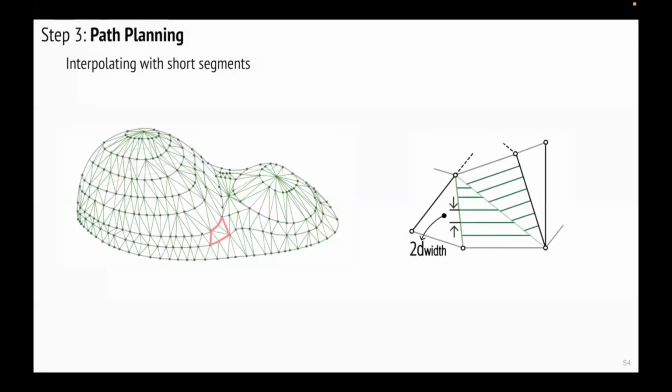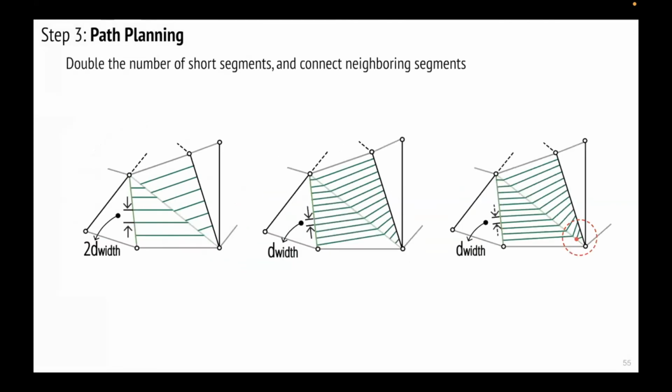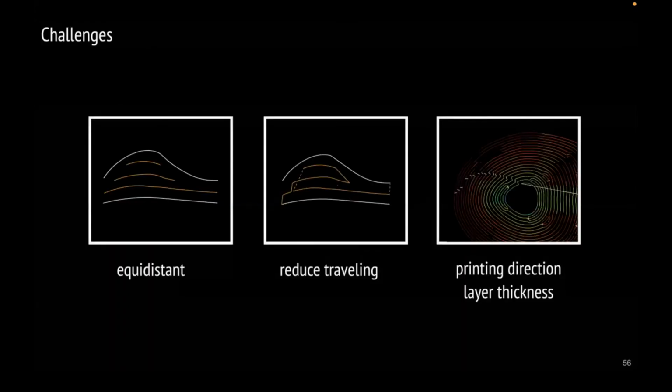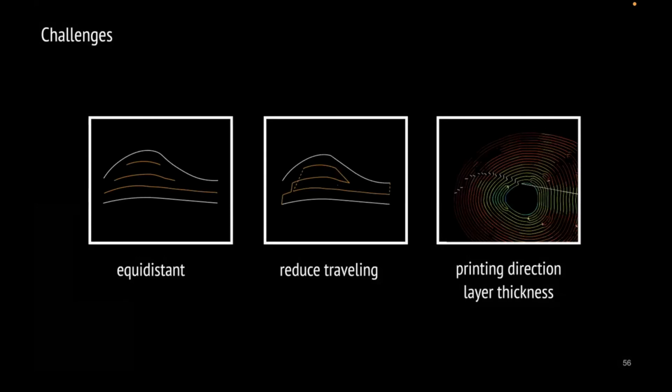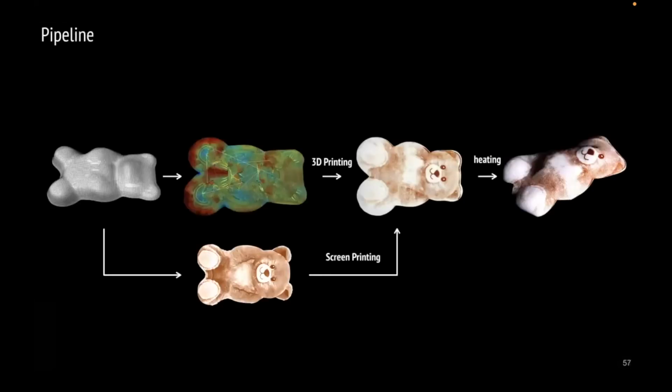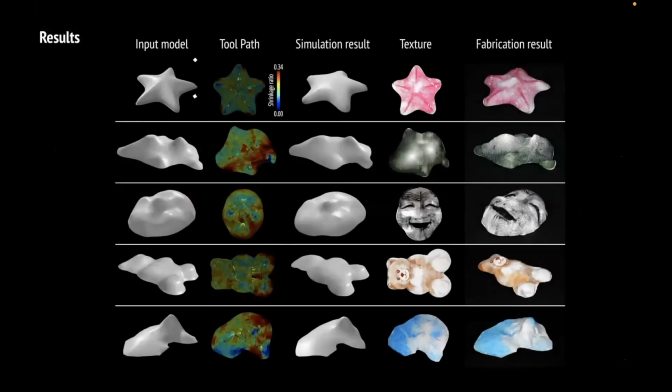And then there is a flattening algorithm to flatten the mesh from left to right, and at the same time capture the contraction and elongation ratio of all the parts. And then there is a specific toolpath planning method, because in 3D printing, you have to do everything in one stroke. You cannot have discontinuous lines, but you still need to fill the whole surface along the direction we assigned. So there is toolpath planning, and eventually what you input is just a 3D model with color texture, and what you output is a 3D printing pattern and the color pattern. And that's the end result.